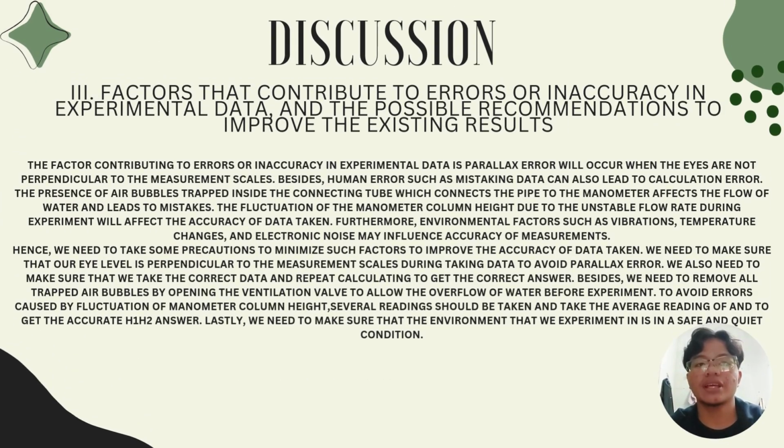For the discussion on factors that contribute to error or inaccuracy in experimental data and possible recommendations to improve the existing result: the factor contributing to error is parallax error, which occurs when the eyes are not perpendicular to the measurement scales.